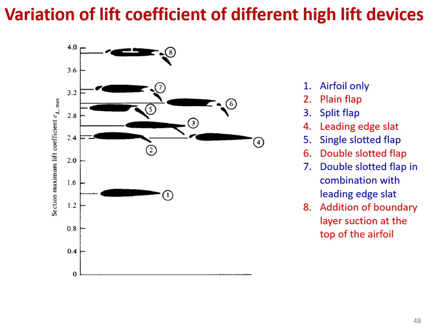These high lift devices are going to have different effects on your airfoil, and you have to choose wisely how much of an increase you want to see in your lift coefficient, and how much complexity you want to add to your system, because this is a very complex system. Manufacturing and maintaining this is much more complicated than the regular airfoil.